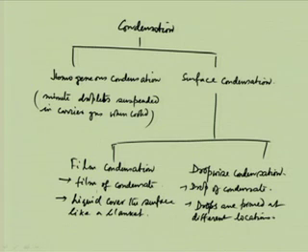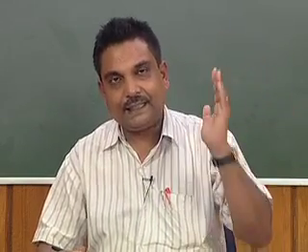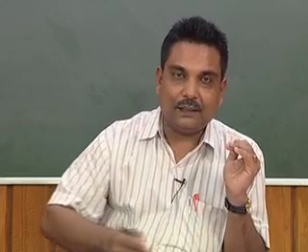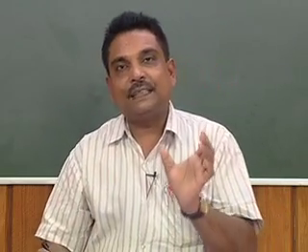okay. Now, what happens is, in this case, if there is a gravity flow, and it is a vertical plate, then once the liquid is condensed and formed, it will gradually come down with the force of gravity and drain out, and the layer will continually exit. As we go down, in case of a vertical plate, the thickness of the condensate film will go on increasing.